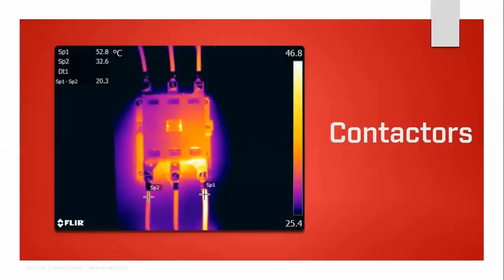And just going back here to something of a contactor, if we have a look at this contactor, we can see that the right-hand phase is much warmer than the others. We've got to ask ourselves, what is the problem here? Could it be a load imbalance? Could it be a loose connection? Or the third option, could it be an internal contactor fault? I'm going to give you the answer to this in a moment. We've only got a couple of slides to go. So, could it be an imbalance, a loose connection, or an internal contactor fault?